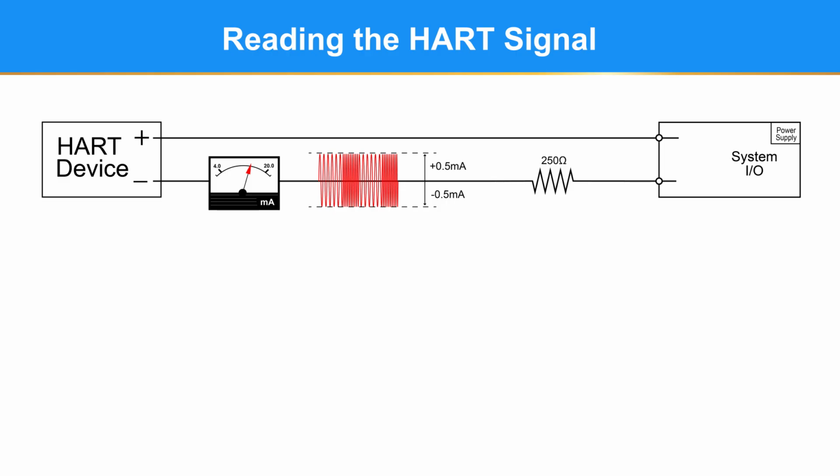The reason the HART protocol became the industry standard is that you can only measure milliamps in series, which means you would have to disconnect wires and place the reading device in the loop to read the milliamp modulation. Not very friendly and maintenance intensive. This is where the required 250 ohm load resistor comes in.